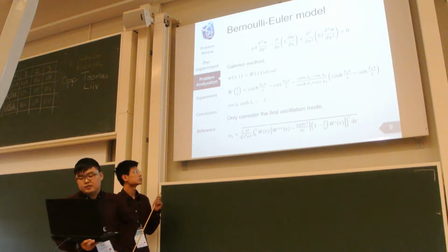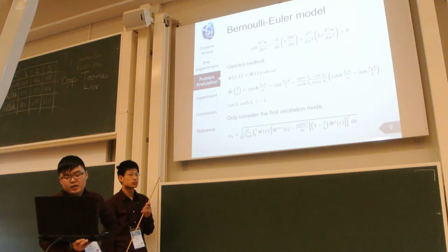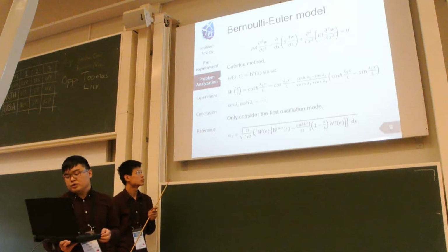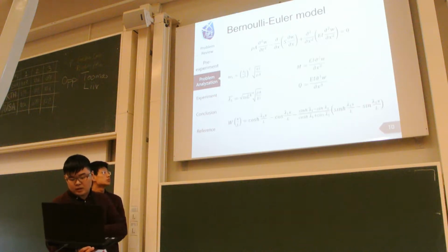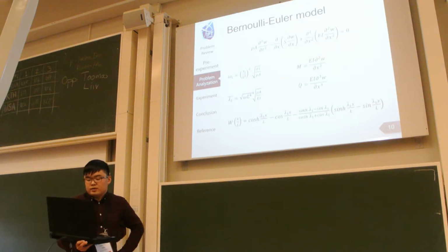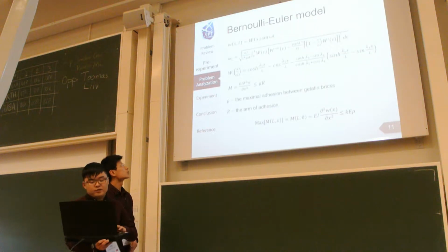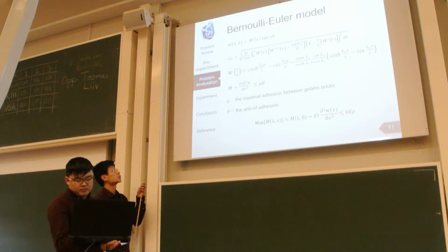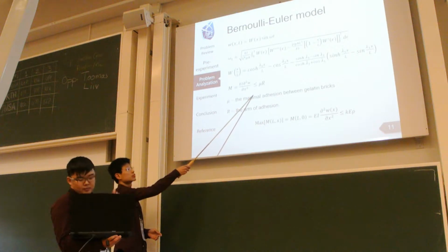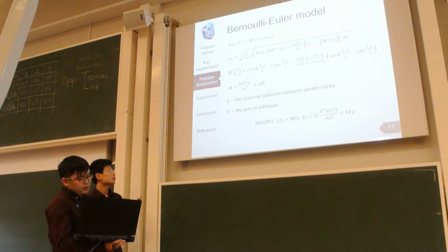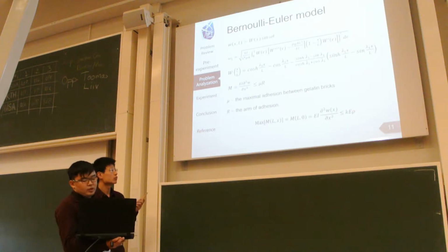When the axial force is not 0, the equation has no analytical solution. Here we use the Galerkin method to get a numerical approximate solution of the ith order inherent frequency. Using the approximate solution, we calculate the amplitude of the first order natural frequency. Our final results are shown above. The bending moment at each point of the tower can be calculated with this equation. And we found the bending moment at the bottom is always the biggest during oscillation.